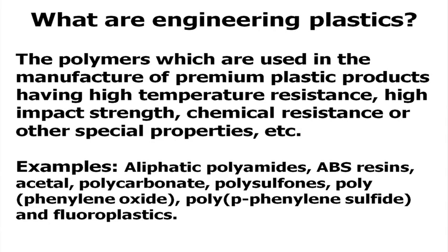Now, what are engineering plastics or engineering polymers? The polymers which are used for the manufacture of premium plastic products or polymeric products having high temperature resistance, they must have high impact strength, they must have high resistance to chemicals and solvents, or they should provide other special properties like flame retardancy or fire retardancy or high abrasion resistance, or they must be resistant to extreme temperature environments, including the cryogenic temperatures, etc.